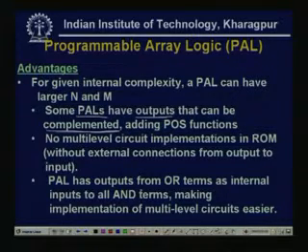PAL has outputs from OR terms as internal inputs to all AND terms, making implementation of multi-level circuits easier. So, here it is possible to get the multi-level circuits. It is a programmable AND, so we can take the worst case or exhaustive case of all possible minterms, and then implementation of multi-level circuits is easier using PAL. But normally in PROM this type of connection cannot be done, because here it is a fixed AND and only programmable OR.